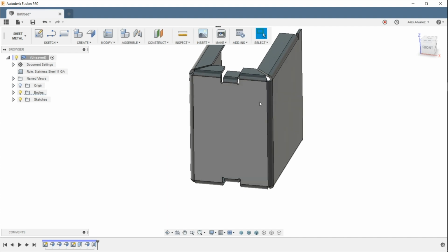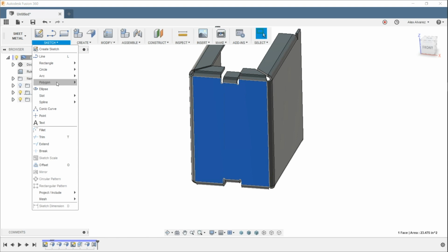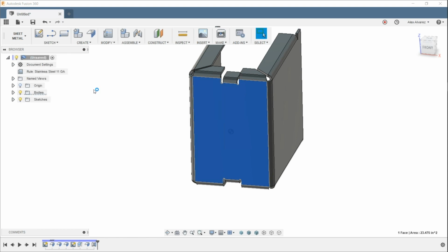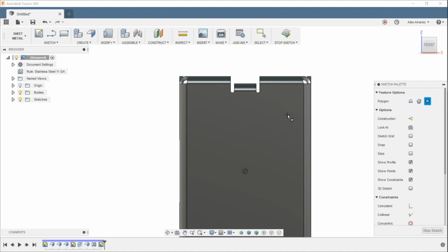So now we had some sort of a shape over here, right? That was essentially just patterned across the front face, and then the hole. So those are going to be really the last 2 features that we have. So let's go ahead and create those. Again, we want to go to Sketch. It's going to be a polygon in this case, inscribed. And let's just create that arbitrary shape somewhere along these lines.